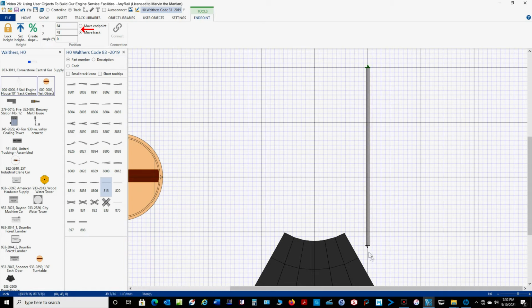And you would think that since I'm rotating clockwise like this, for those of you who remember clock faces, that I would go, well, this is 180 degrees, and I want to go to 175 degrees. That isn't the way it's going to work here. I need to rotate around a center. If I rotated here, the track would swing this way from the top. I need to rotate it from the top, which means I have to go to 355 degrees, and now I've got the correct rotation.